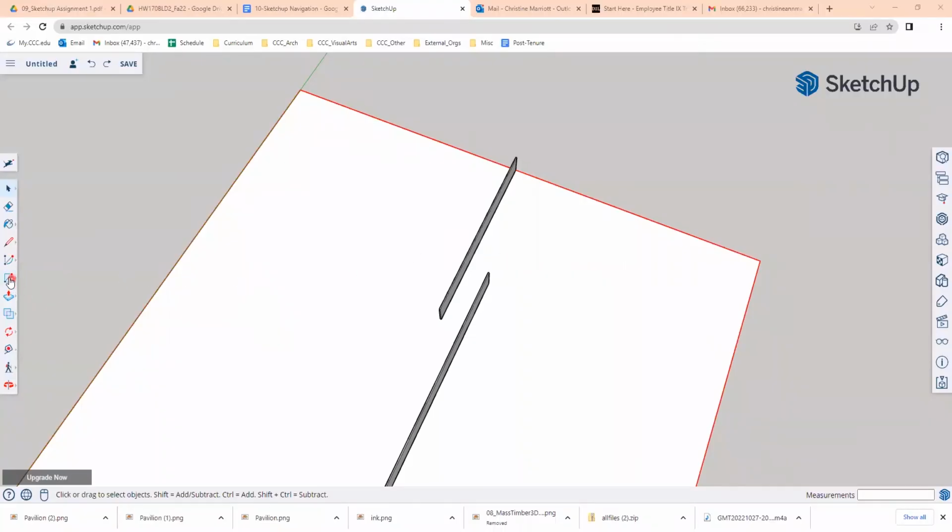The next wall I'm going to make, I'm going to move it to a diagonal or rotate it so it's not aligning with either of these walls. I'll start off though by just drawing it in relationship to those walls, and then I'll use the rotate tool to create the angle. So I'm going to make this one, we'll say 5 inches by 40 feet. Enter.